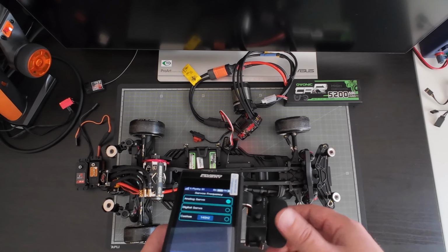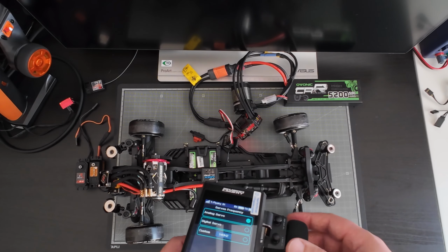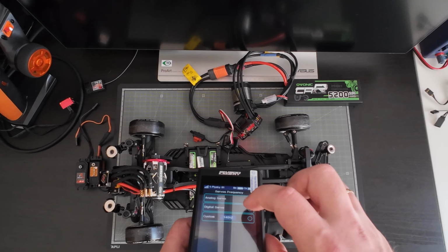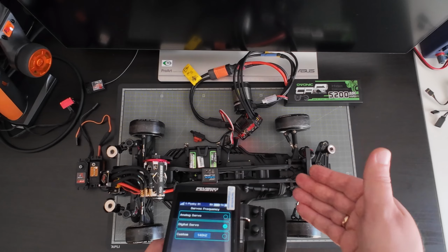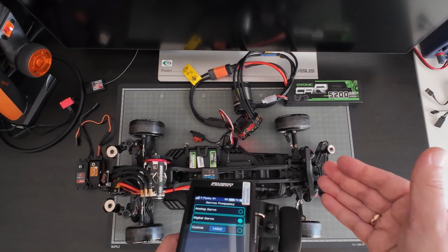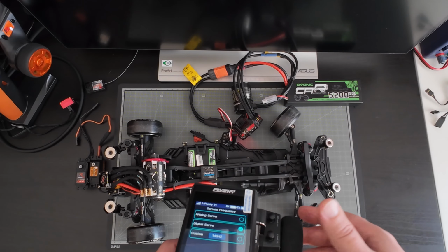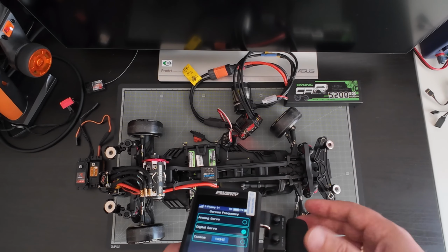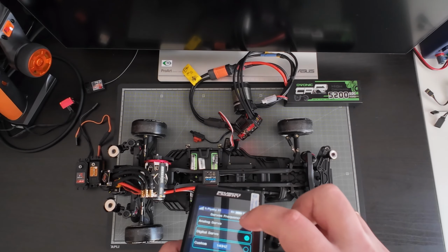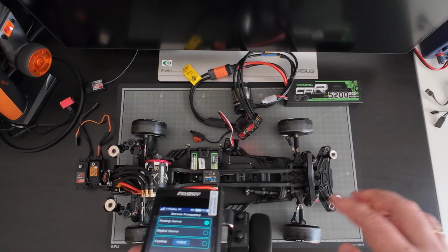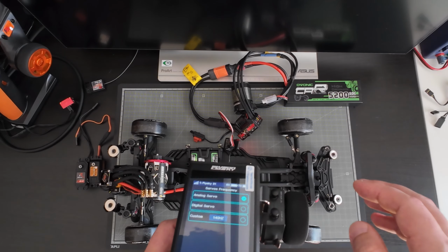Now in analog mode, you can see the steering is working perfectly fine, no issues. If I now switch to digital servo, we are at 333 Hz, the same as Yokomo version 3 and OMG version 3 and Yokomo version 4 were pushing out, and you straight away notice that we are having the same issues that we have with those two specific gyros. So you see that this specific servo cannot handle those 333 Hz.